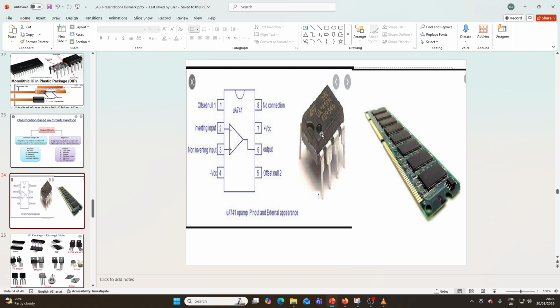In the case where you see the U shape but no dot, or you see a dot and no U shape, you know that you start your pin 1 from your left side. It moves in the U shape like this. So we have pin 1, pin 2, pin 3, pin 4. Then you start pin 5 just opposite to 4. You don't start it from the top here. Otherwise, you are going to make a mistake with the terminals and you can easily cause a short circuit. So 4, then 5, 6, then it goes up like that.